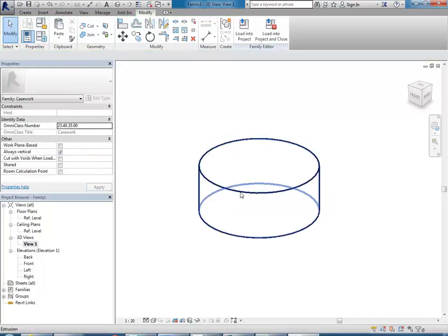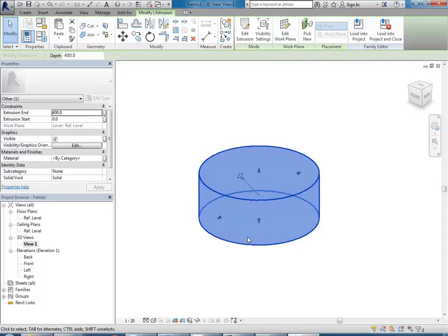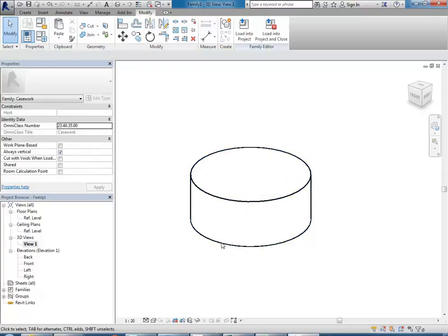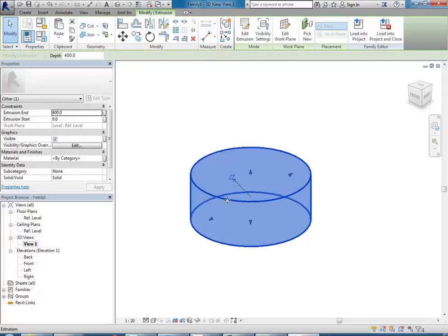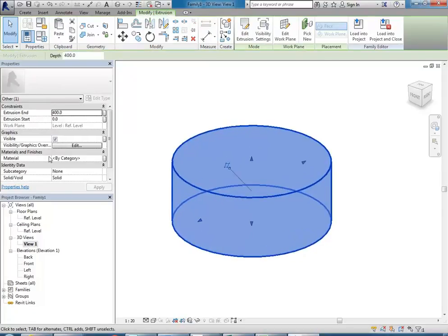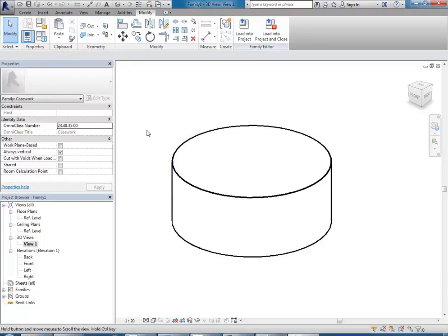Okay, so then I'm going to just give you a bit of an intro into parameters. We'll do a lot more on it later. So for interior projects, this is a parameter you will need to make continually. You'll need to assign material parameters, because for interior design a lot of the work is specifying materials, and you'll often have repeated elements in your designs where you need to control the materials, and often the only difference between these objects is going to be the material. They'll be the same shape, but then you might have some of them that are different colours or different finishes altogether.